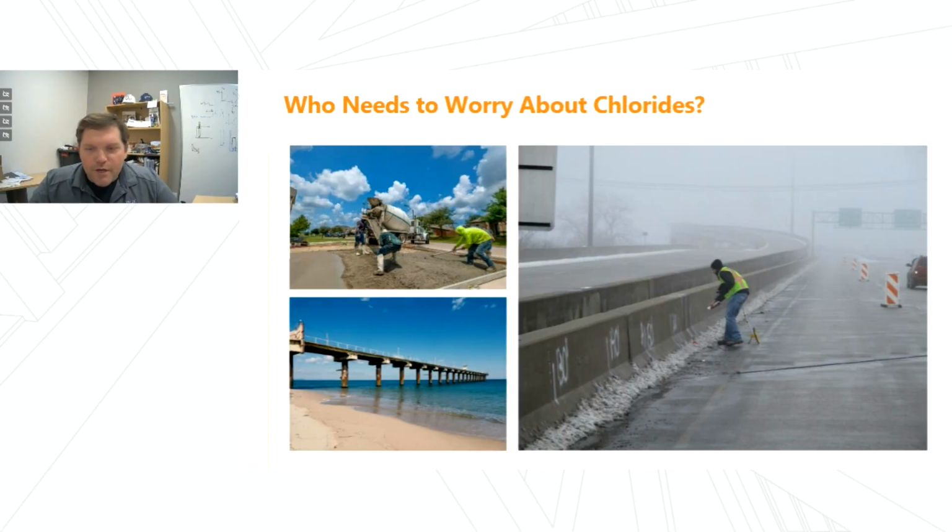So what does chloride contamination mean to you all listening? From a new construction standpoint, obviously suppliers, specifiers, and engineers need to understand the material makeup, whether or not chlorides might be part of the contamination of these materials that are going into new structures. For those that manage existing structures, it's important to understand what chloride contaminations might exist, determining how that's going to look going forward, and what kind of exposure conditions and future durability risk we have, and that might factor into how we plan for future asset management programs.